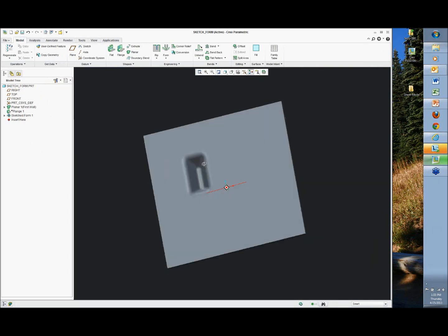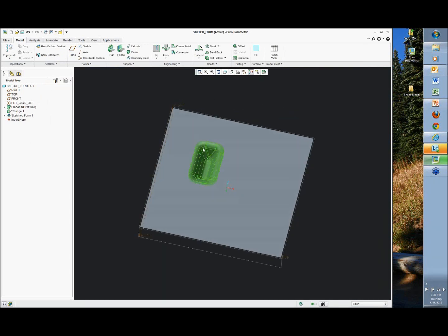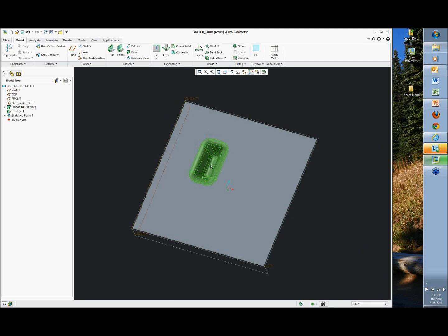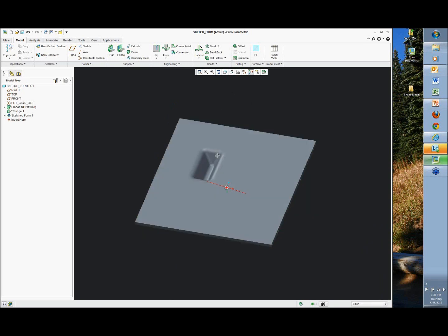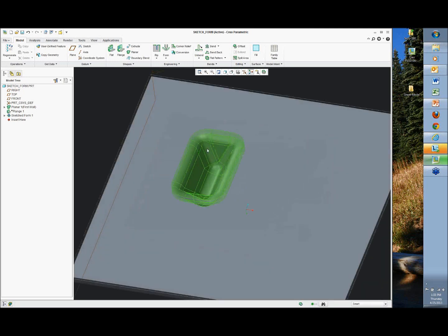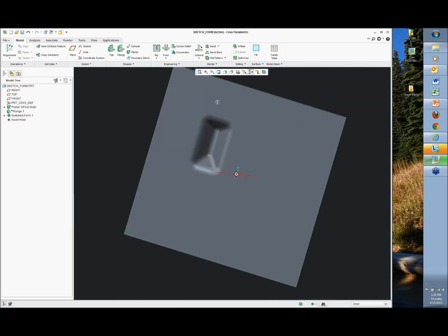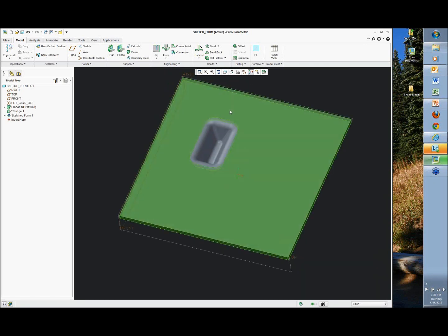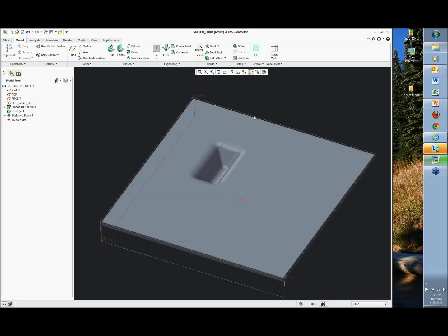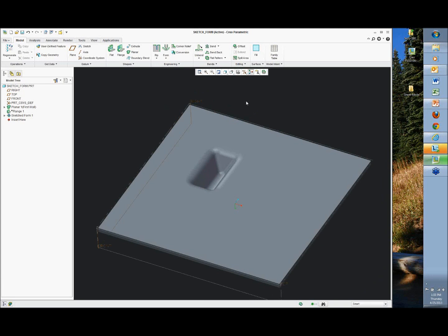The only issue with all of this stuff is Pro/E does not do a good job of figuring out the flat size of that sheet after the form, right? So if you took a piece of metal and pushed through like that on a piece of sheet metal, it would definitely distort the edges over here because that metal's coming from somewhere, right? It's got to pull it in from somewhere. So that's the one thing that I still have been waiting for some better answers on, but not yet.